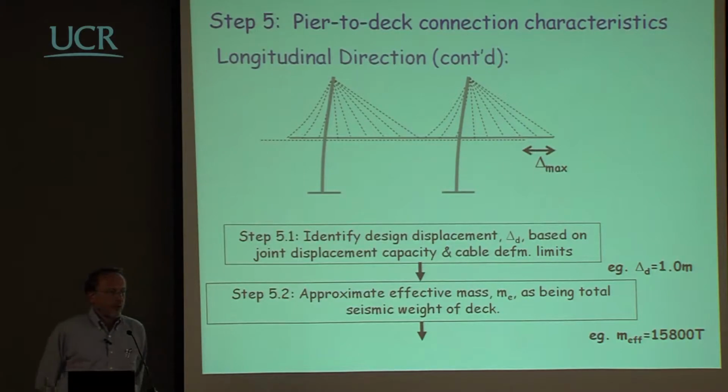Well, if you accept to reason in terms of displacement, what you will do is what we've been discussing this whole day, which is to decide what longitudinal displacement you consider acceptable for this deck. And this is now something that could be related not to strictly earthquake problems, but could be related, for example, to the problem of joints at the end of a bridge, to all sorts of problems. But anyway, you should start from there and say, this is the level of displacement that I accept. For example, let's assume that we will be accepting 1 meter displacement.